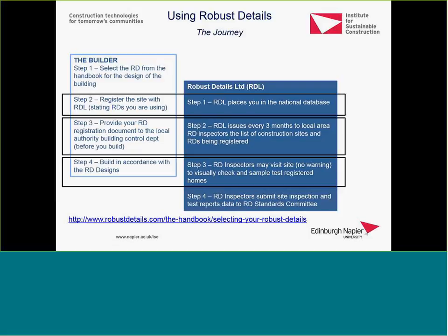If the site manager refuses the Robust Detail inspector entry to the site, the local authority building control can be notified, and the registration of Robust Details from that site can be withdrawn. As a result, that site would move to mandatory pre-completion sound insulation testing on site, and they would have to go through all the various percentages and qualifiers for testing that are required.